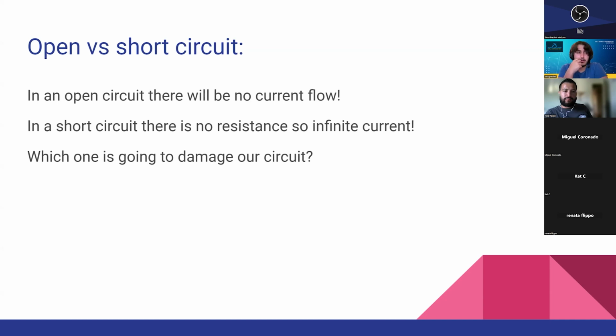So one of the things, we have two things, right? Our power supply is not going to supply too much current anyways, right? So it's not a 2 amps, let's say, power supply that can actually provide that 2 amps to your circuit, right? So the second thing, as other people said, there is a resistor, right? And each resistor has a wattage rating, right? So they can handle up to 1 watt, let's say, I don't know, 0.5 watt, right?